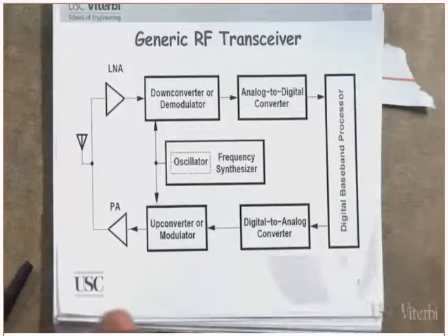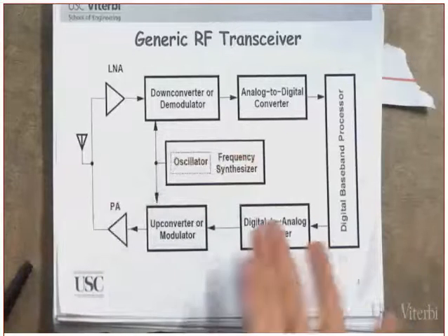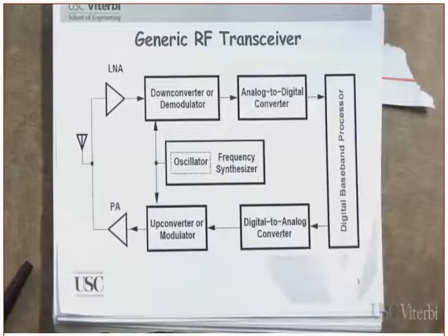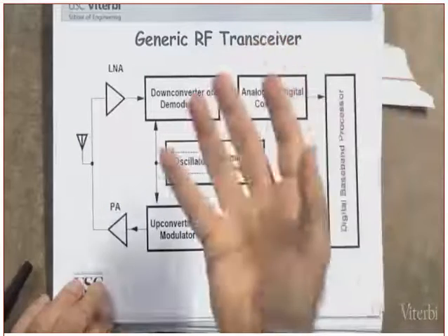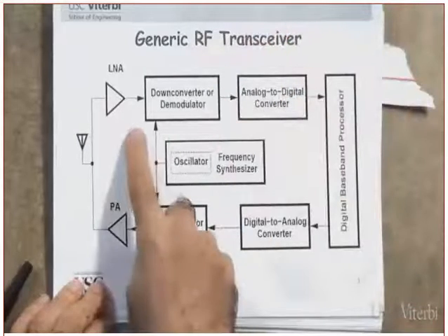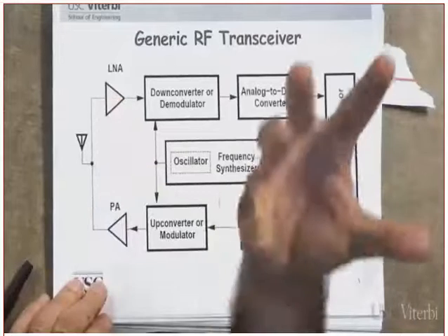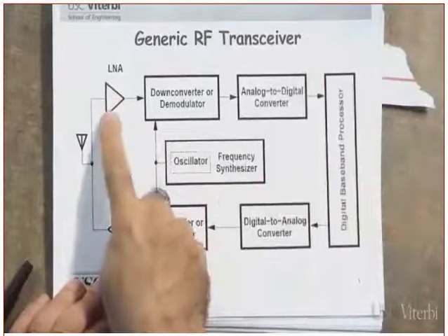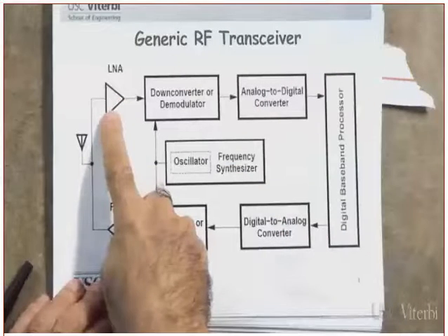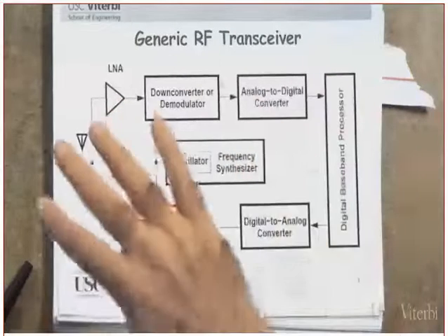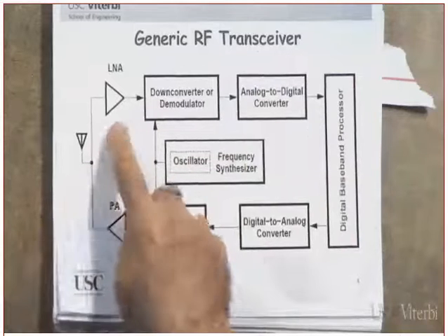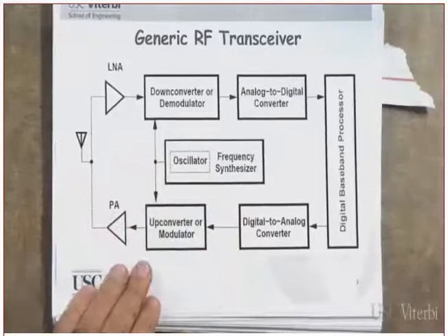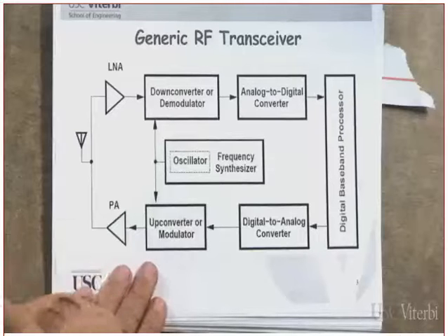Did you understand what I just said? They found it to be less than 5. Something must have happened. Why? Because the amplifier is going to amplify the signal and the noise the same way. There must be some noise which was added internally, because of the electronics in the device itself, resulting in the signal to noise ratio going down, degrading a little bit. Clear? We would like the device to add as small an internal noise as possible. Clear? We'll talk about that again in detail.